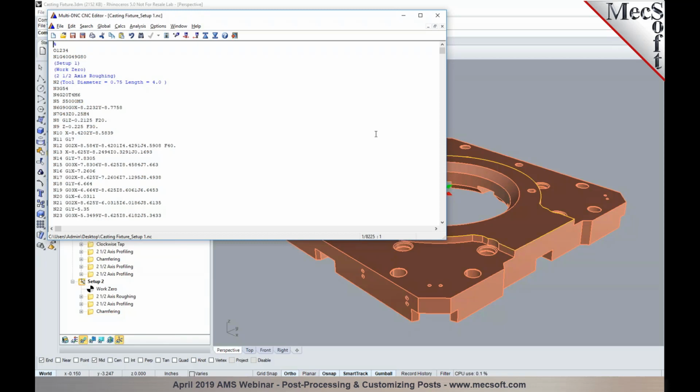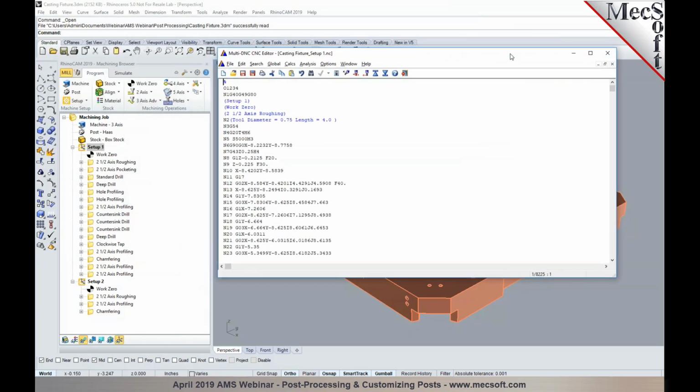One important note here: whatever program that you set up in that dialog needs to be able to take the name of the G-code file as a command line argument. If that executable does not accept the name of the G-code file as a command line argument, then all you will do is launch that program and it's not going to read that file.